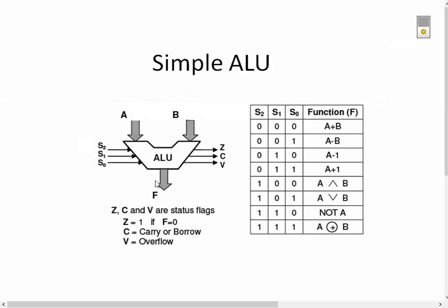By the way, this is kind of the symbol that you will typically see of an ALU, and how it's used is you oftentimes are going to have a couple of registers. So essentially what's going to happen in our ALU, I'm going to have two registers. I'm going to load those registers, and by the way, we'll talk a little bit about what a register is in the next unit, but what a register is, it's basically a memory structure that's going to hold one word of whatever number of bits I'm dealing with. So essentially I have an A register and a B register, and this forms that A input, B input that we saw on the previous screen.